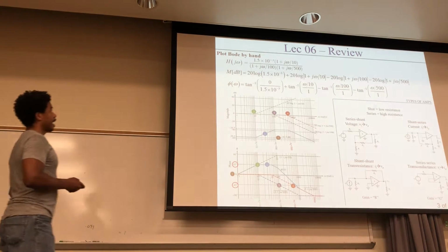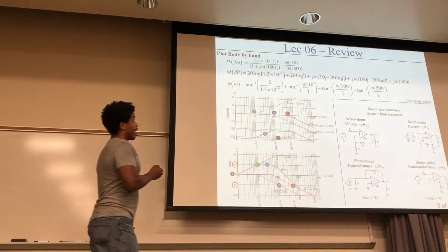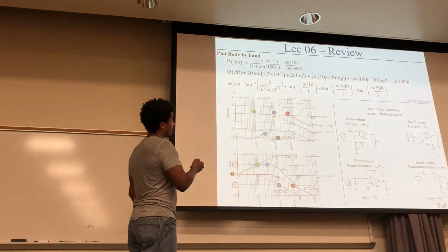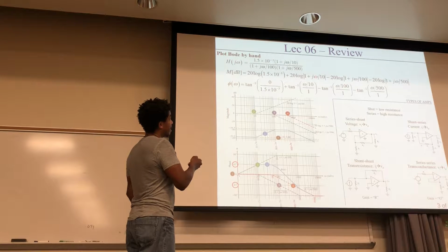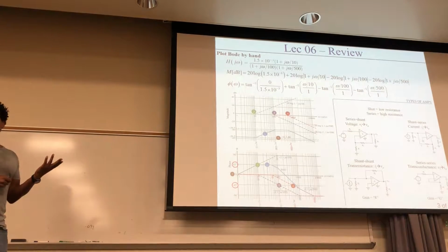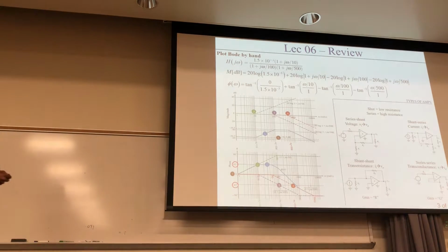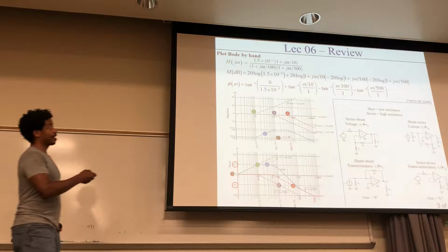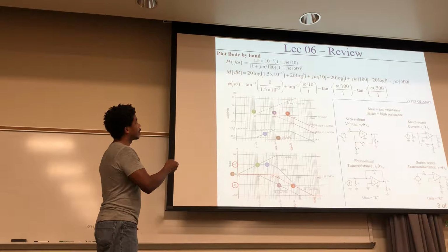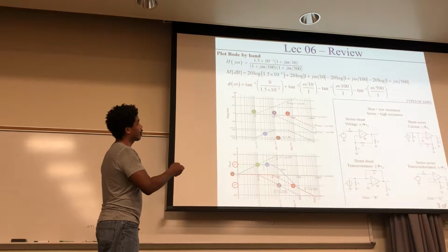Okay? And of course, if you look at the magnitude, every time you have this right here, if you look at the cutoff frequency, which is when that frequency is equal to whatever is in the denominator, this becomes this j, because that becomes 1, right? And so you have the magnitude of 1 plus 1j, which is the square root of 2, and of course, what's that going to be in decibels? 3 decibels, right? So if it's right here, it'll be 3. So over here it's like minus 3.